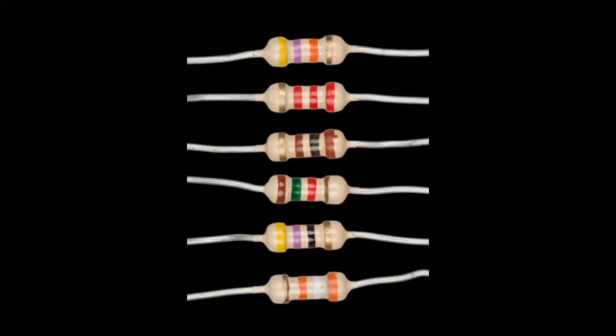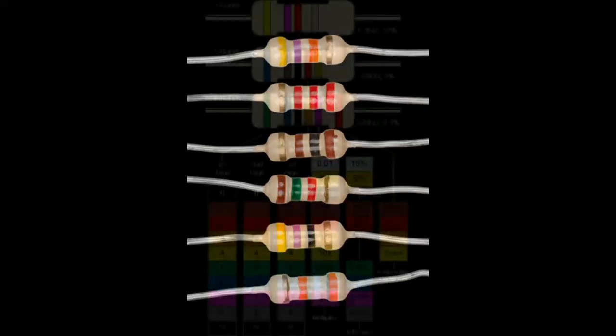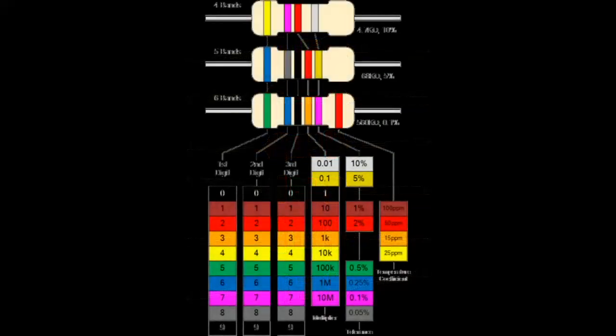It will be seen when looking through a component supplier's list of resistors that they are available in different tolerances, which means the resistance value may not always be exactly as indicated on the body of the component. They are available as 10%, 5%, 2%, 1%, and can even have closer tolerance.